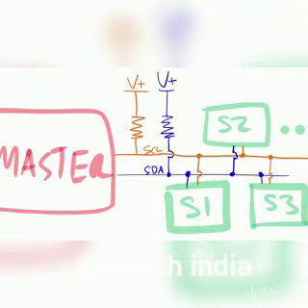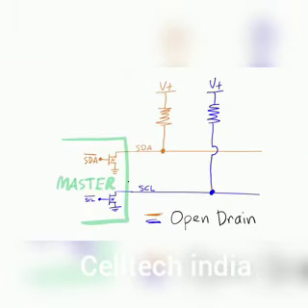So here we have 2 wires, the serial clock and the serial data. That's SCL and SDA. The reason that the bus can communicate with 127 devices on only 2 wires is because those wires are open drain. Open drain means that the driving side only drives low. Each of the wires has to have a pull-up, which means that when the line isn't being driven low, it gets pulled high. Now, if you see a schematic one day and you see 2 resistors pulling up to the power rail, you'll know why that is.